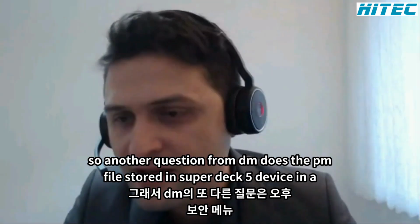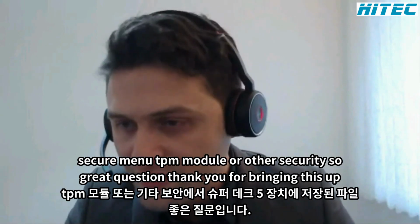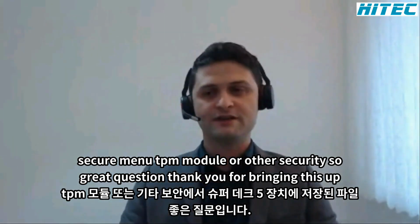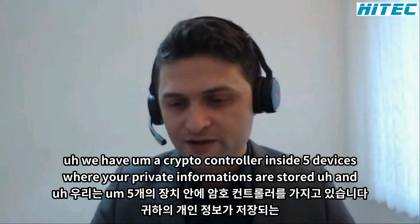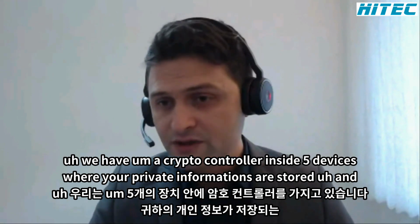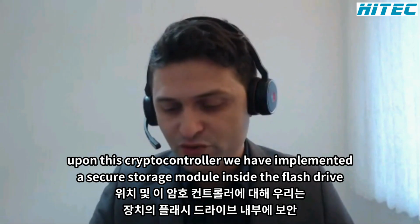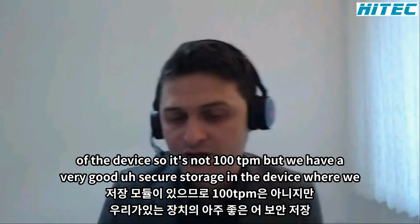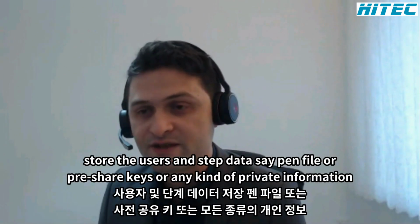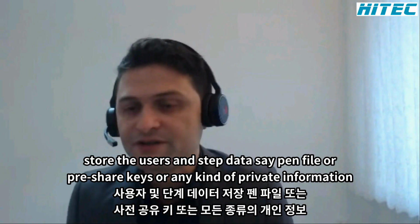Another question from DN. Is the PEM file stored in the SIPROTEC 5 device in a secure manner, with a TPM module or other secure methods? Great question, thank you for bringing this up. We have a crypto controller in SIPROTEC 5 devices where your private information is stored. On top of this crypto controller, we have implemented a secure storage module inside the flash drive of the device. So it's not 100% TPM, but we have a very good secure storage in the device where we store the user-sensitive data, say the PEM file or pre-shared keys or any kind of private information.